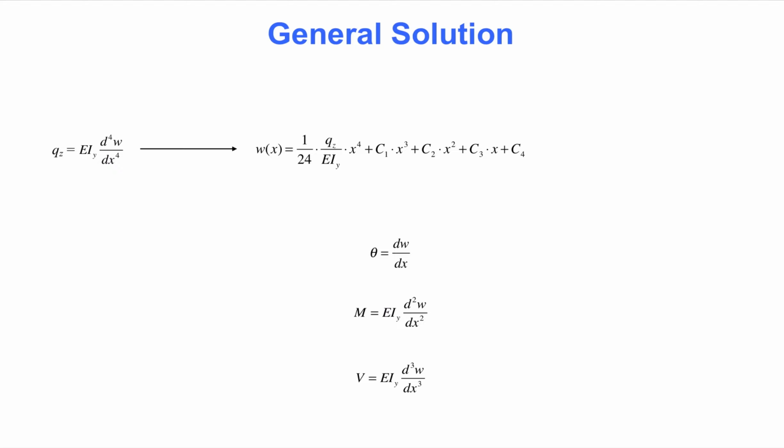Although the differential equation for beam bending is rarely solved in everyday engineering, it is a simple exercise, which is instructive for the study of reference cases. Also, the solution of the differential equation is the starting point for the selection of shape functions in the finite element method, which is covered in another short course at terje.civil.ubc.ca Toolbox. The shape functions used in the finite element method are often approximate, while the solution to the differential equation reveals the exact deformed shape.